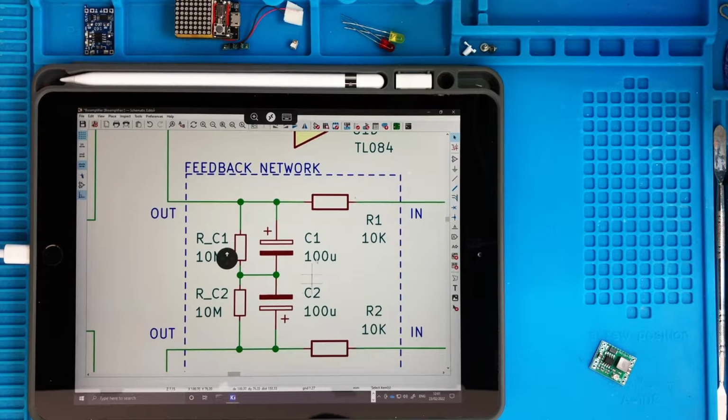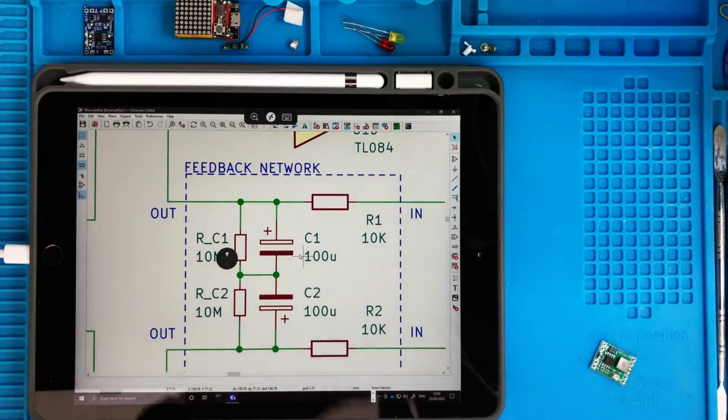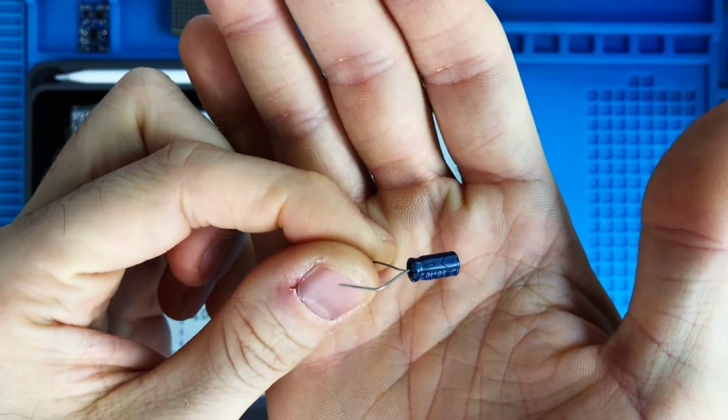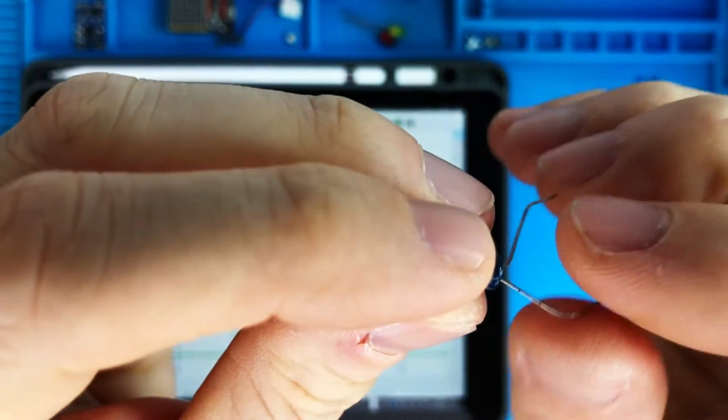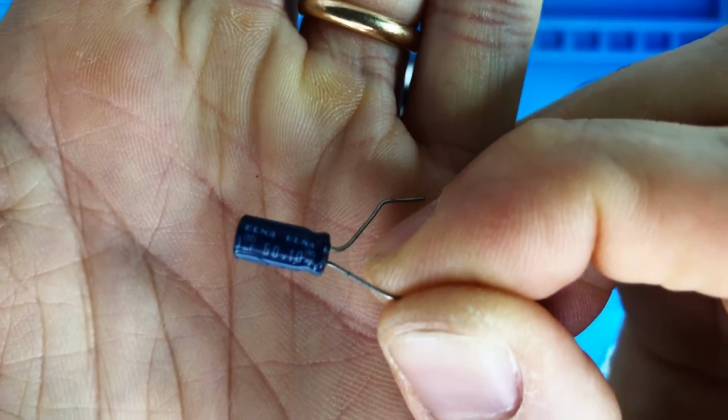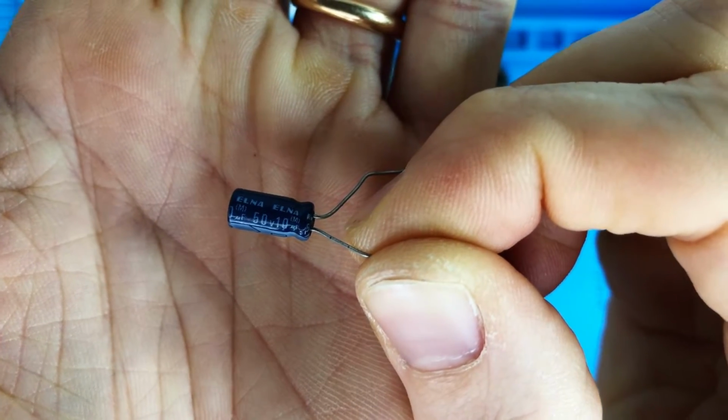The part number, which is also called the designator in this nomenclature of schematics, tells you which is which. The other label is for the value. This is a resistor, and the resistor has only one value, which is its resistance. It's not like this for capacitors, for instance, because we have already met those electrolytic capacitors. They have two values: the capacitance in microfarads and the maximum voltage.